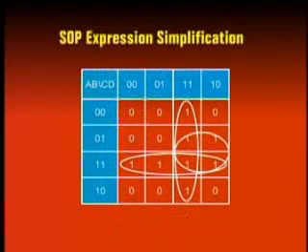An appropriate way to implement the adjacent ones detector circuit is to simplify the SOP, or the sum of product Boolean expression represented by the function table, and then implement the circuit based on the simplified expression. The function table information is directly mapped to a 4-variable Karnaugh map. The ones are grouped together, forming 3 product terms. The 3 product terms are AB, CD, and BC.